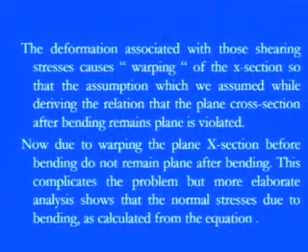But whenever non-uniform bending is there, it always gives a different kind of shearing force for different cross sections, and corresponding shearing stresses are there in the material. The deformation associated with the shearing stresses causes warping of the cross section, so the assumption which we made while deriving the relation, that a plane cross section after bending remains plane, will be violated, because once it is warping, it is deviating from the original position.